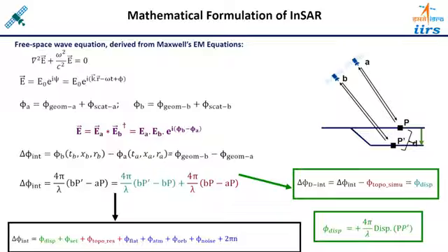So decorrelation noise is there for a given set of images, whatever you have chosen. Now you cannot further minimize the baselines. Whatever baseline has been chosen will remain, and the decorrelation corresponding to that baseline will remain in the signals. So that much noise is there in the calculations. That is called the decorrelation noise.